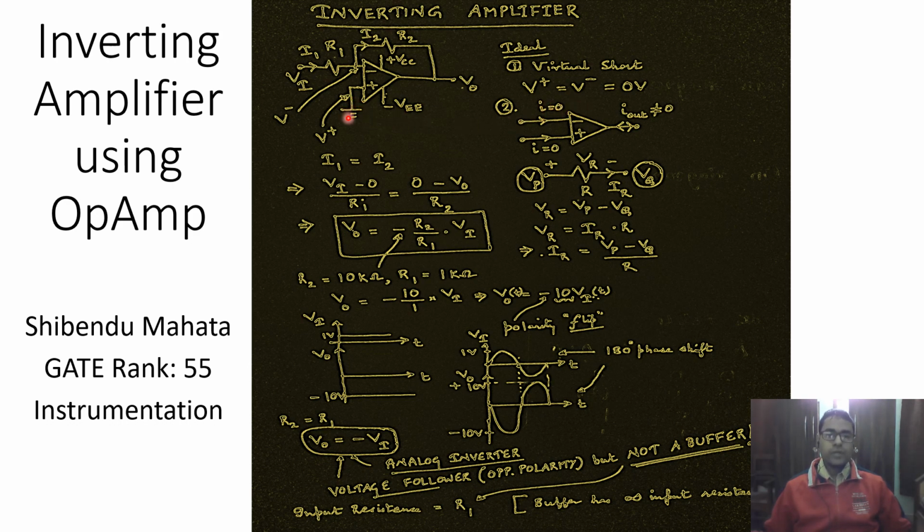And so what it implies is that the voltage at the non-inverting input terminal is the same as the voltage at the inverting input terminal. Now, this arises due to the infinite voltage gain, or open loop voltage gain, of the operational amplifier. And in the present case, because the non-inverting input terminal is connected to ground, it is at 0 volts, and therefore at V minus we should also obtain 0 volts. So this is the first concept.